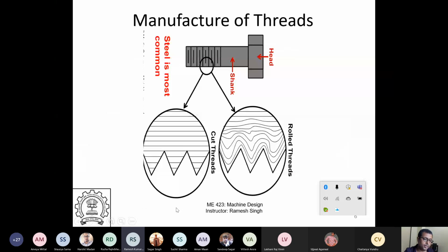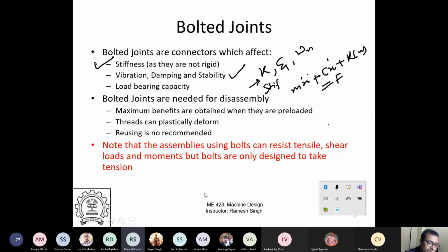Okay. So this is what I'm talking about. So Ft, right? Meaning how my system will vibrate, at what frequency, what will be the amplitudes. So basically, you will get a solution as xt here if you solve this differential equation. How is the displacement? Now this is a function of c, which is some sort of a damping function, of damping, which is zeta, and k stiffness, and of course mass is also important, right? So basically, the moment the stiffness changes, your vibration, your damping, nature of damping will change.